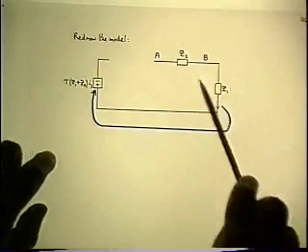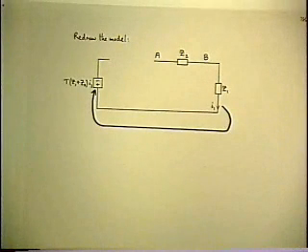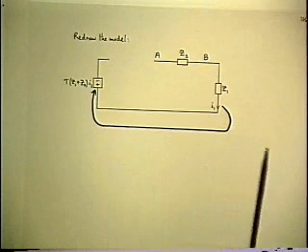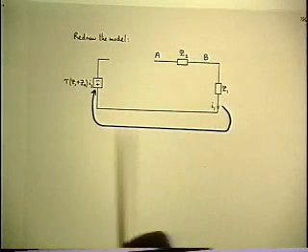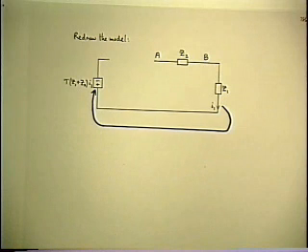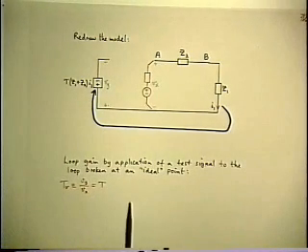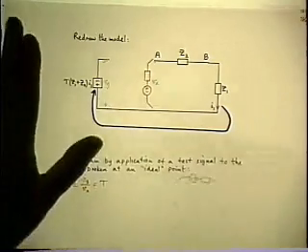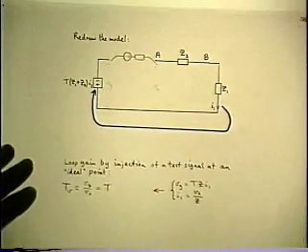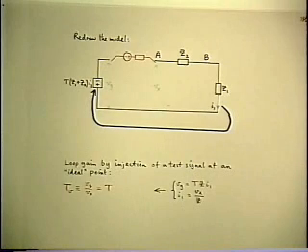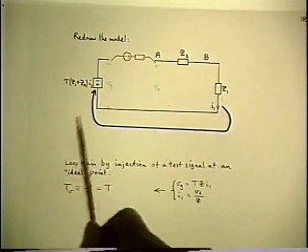At the same time I've separated the two boxes, I've taken away all the surrounding clutter to do with the feedback amplifier. It's not necessary anymore. All the important stuff is embodied in this picture. So once again, I can say whichever injection method I use, whether I apply the test signal to that point, I get the right answer, and if I inject the test signal at that point without breaking the loop, I still get the right answer, because the equations are still the same.